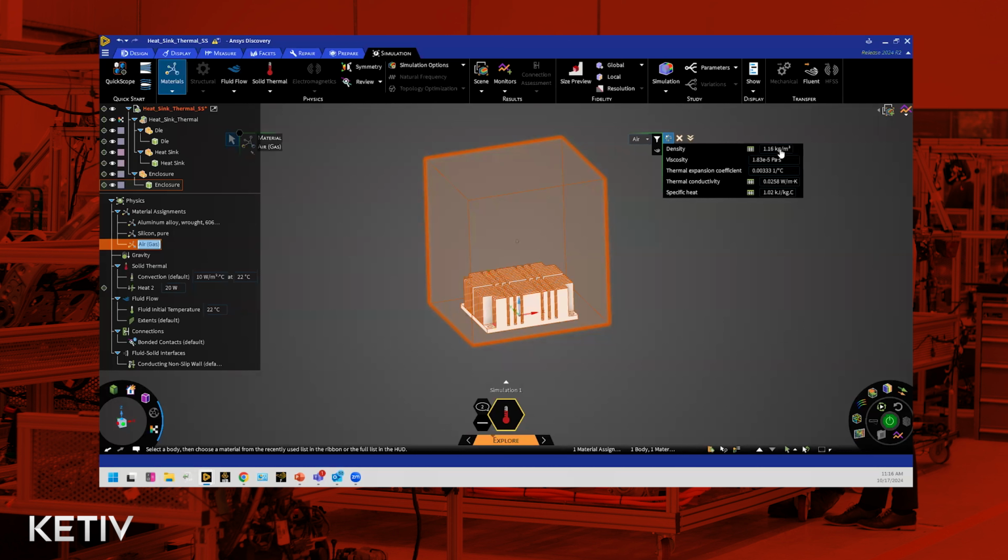It is only valid in those cases when the density change in real life with respect to the temperature changes is relatively small. So in those cases, you can apply this Boussinesq approximation, and that will allow your simulation to usually run faster. This is not just unique to Discovery. You also have the capability of using something like a Boussinesq approximation in other CFD tools, especially in Ansys Fluent as well. So that's what it is doing behind the scenes. If anybody was curious about how it is accounting for density gradients, even with a constant density number.